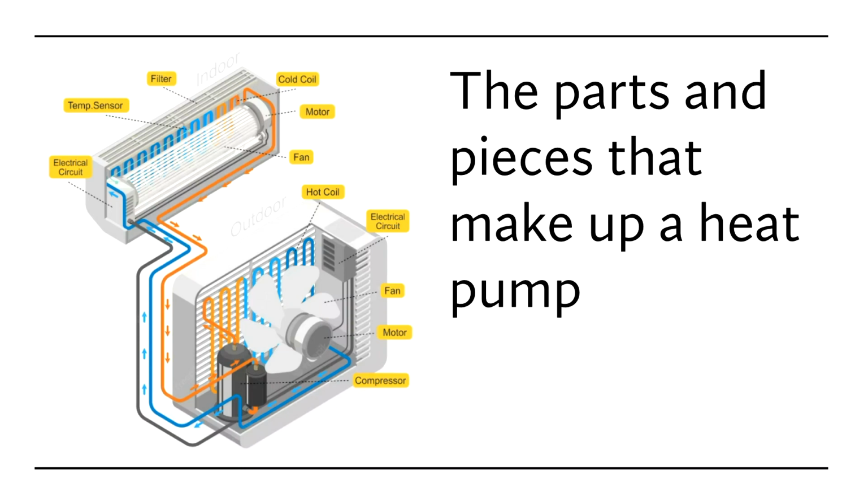The electronic circuits, and this is the inverter unit, and really the heart and soul of the electronics with this is all on the outdoor unit or the inverter. We have a fan that operates on a fake AC circuit that's really DC driven, and gives us the ability to modulate the fan along with modulating the compressor that we have. All right.